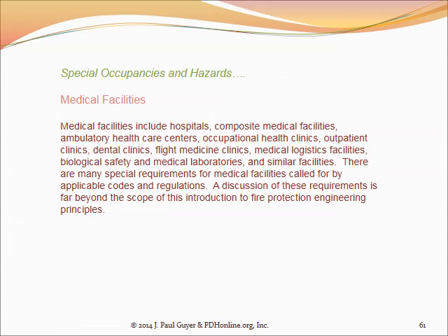And the strategy is that in the event of a fire, the alarm goes off and the staff at the medical facility will move the patients, and of course they are on movable beds, into the area of refuge. The doors are closed and the patients and their attending staff will remain in the area of refuge until the fire can be extinguished by the fire department or the automatic fire sprinkler system.